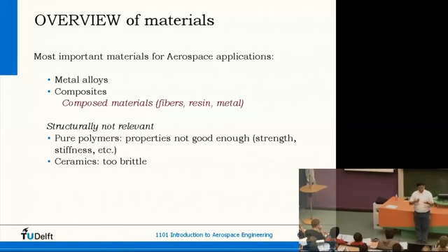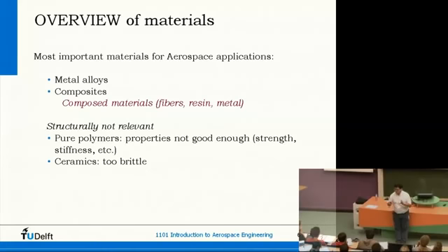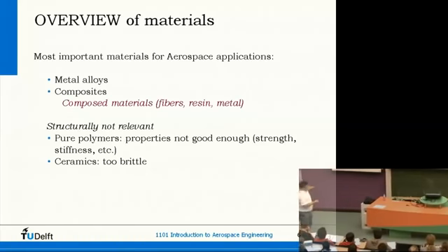It's very strong, it's very heat resistant, but it is also brittle. So if you have an impact in a very specific place, it could crack, it could puncture a hole in it. And that happened in that case. The leading edge was not designed for those kinds of impacts. They were not anticipating. Only very small impacts could be sustained by that leading edge. But there you see how a brittle material can be very nasty if it is not used in the proper way.